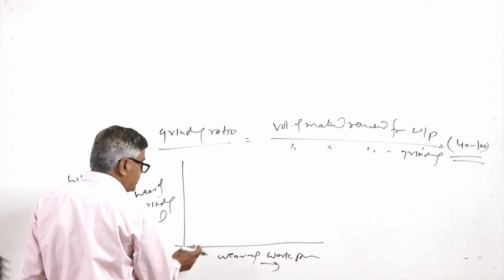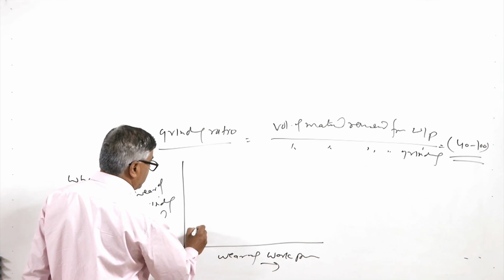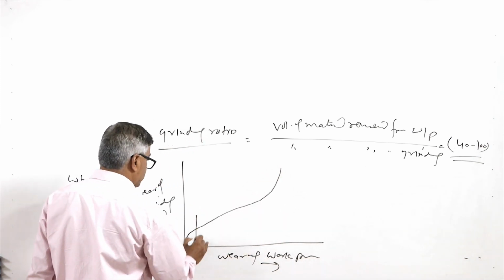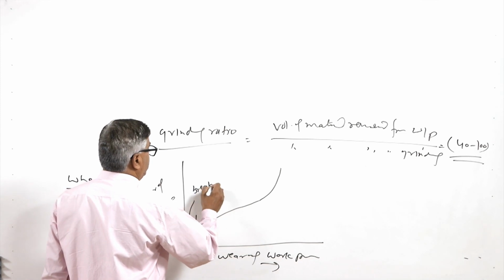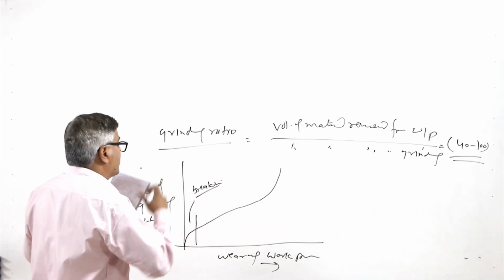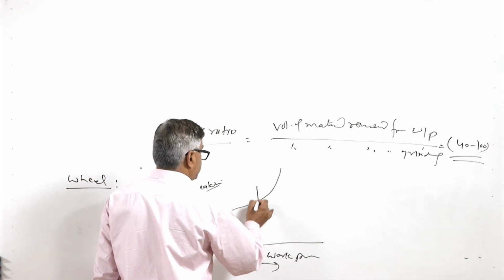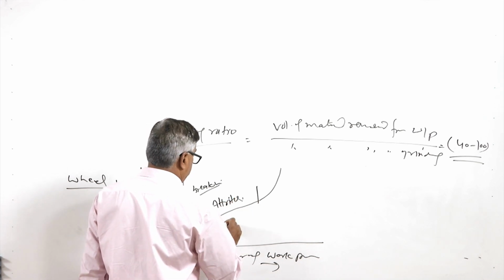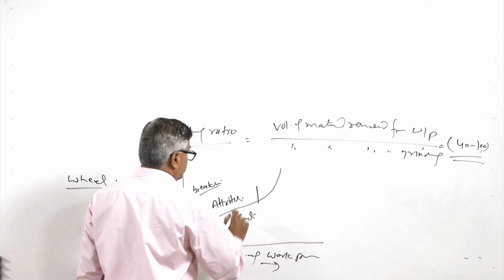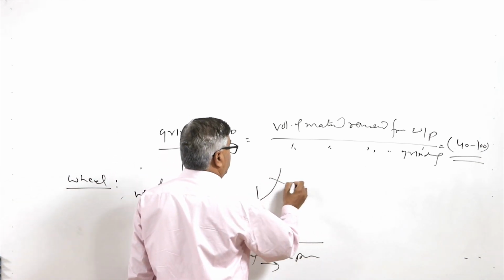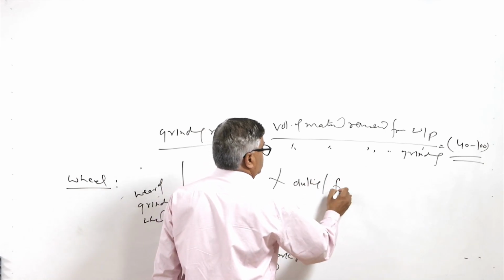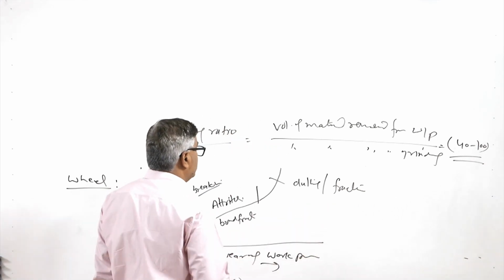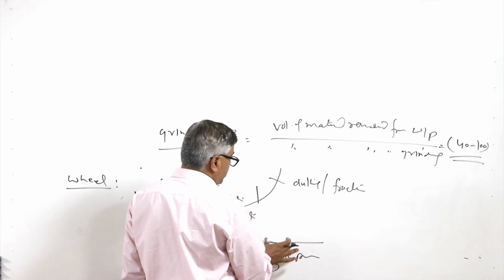So, initially when the grinding wheel is placed in use, it wears out at a faster rate, then the wear rate becomes constant, and then it occurs at an accelerating rate. So, this one is called the break-in period, wherein initially fresh abrasives fracture, and this is the steady state rate, where primarily attrition and bond fracture take place, and the third one where the abrasives become dull. So, the fracture of the abrasives and the fracture of the bonds takes place. So, here the cuttability in the third phase is reduced significantly.